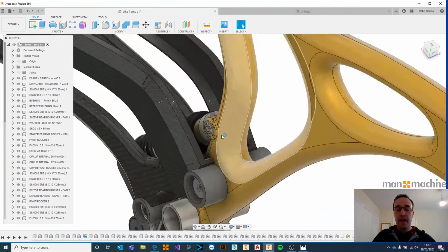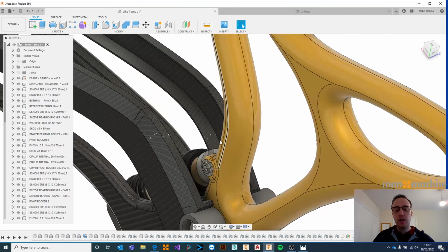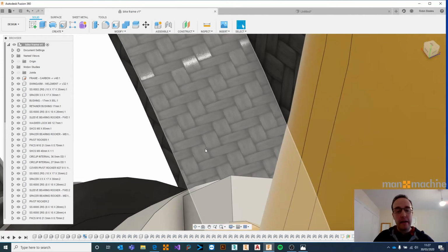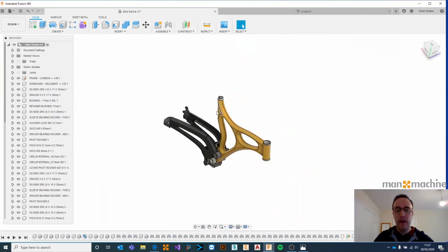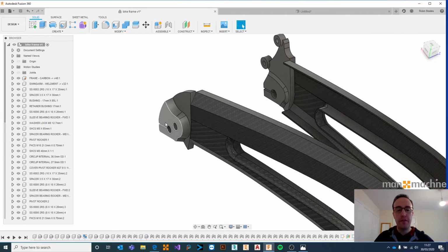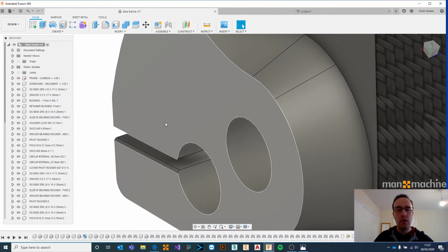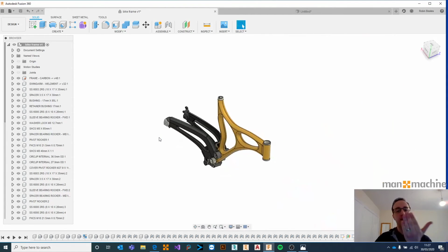So once you've spent a few minutes getting used to how that works, you can also double click your middle mouse button. That will do a zoom extents or a zoom all. So that means no matter where you are in the model, just by double clicking that middle mouse button, that will zoom extents. So that will zoom to everything within your model.